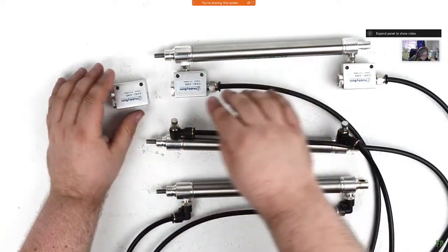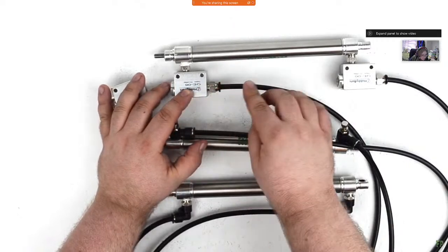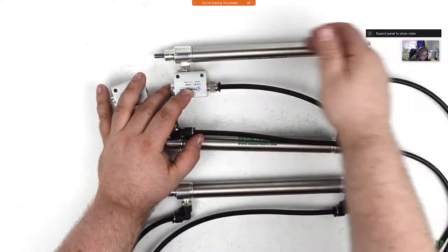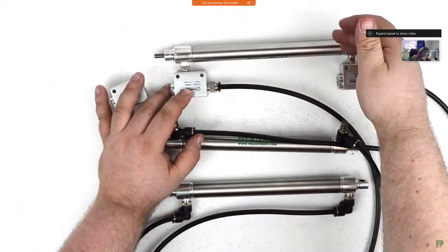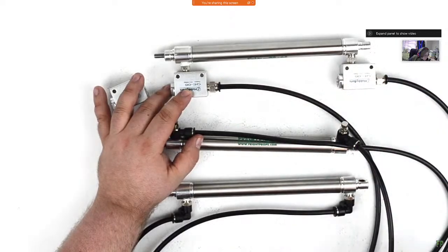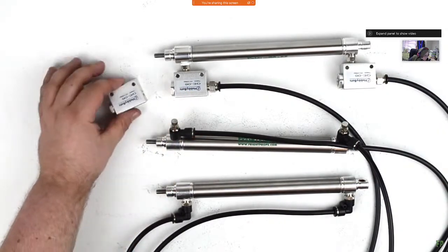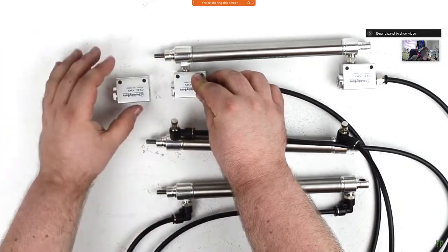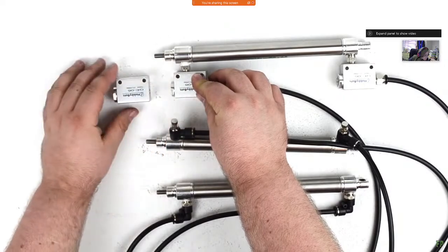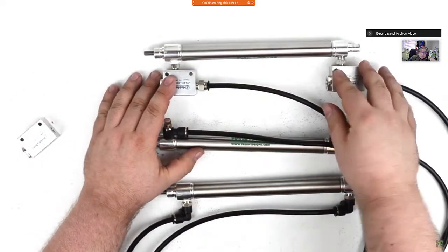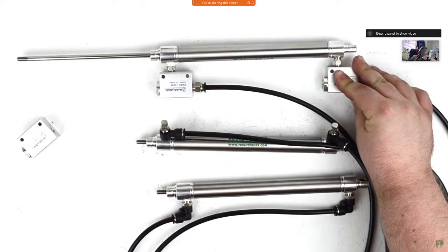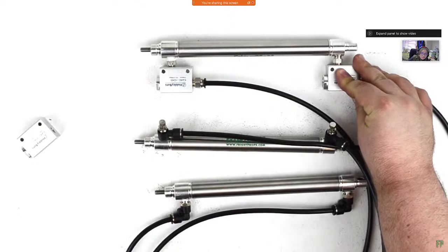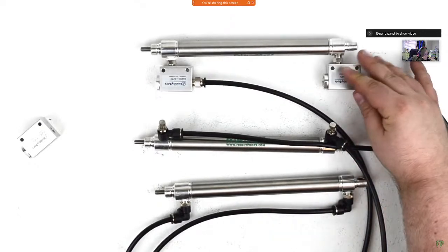Now, how this works is that traditionally, when a cylinder receives air from the solenoid, the air comes into the cylinder, pushes the rod out, and then it has to exit again, back down the air line, all the way to the exhaust on the valve. By using a quick exhaust valve, the air is allowed to exhaust directly at the cylinder connection, which makes it much faster. So let's check that out. So you can see the cylinder extends and retracts much more quickly.